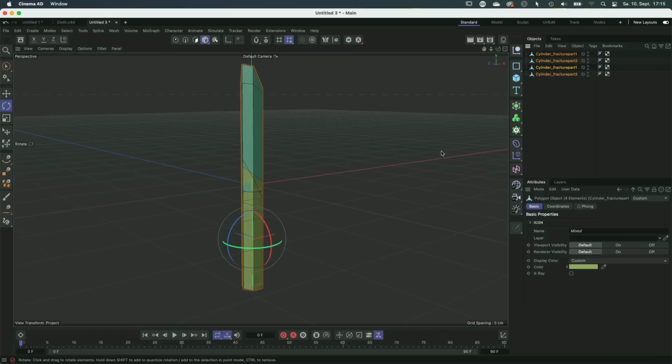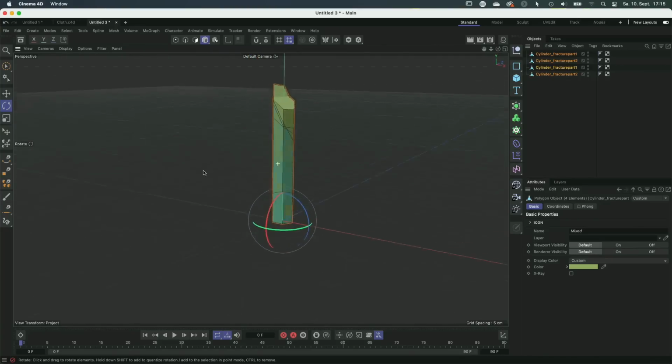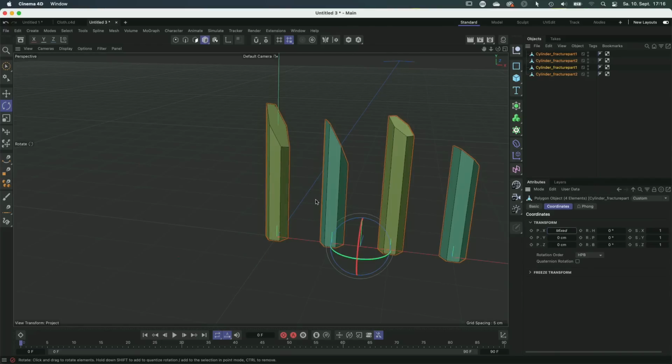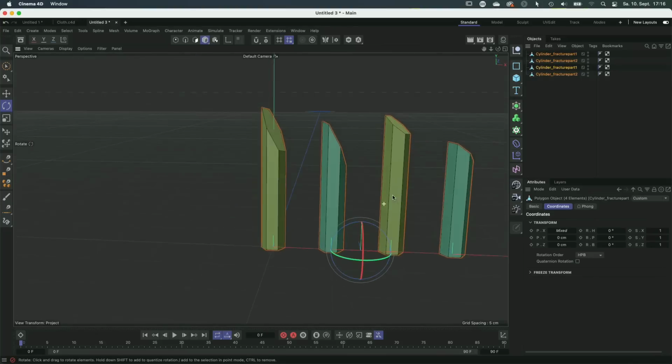Now I can reset the transform here by using the shortcut Alt-0. And you can see that we now have our crystals. So let me place them next to each other so you can see that. I'm going to do that by hitting a Num. Num is going to use the index of the selection, and then I can just multiply that by 5 or something, and I will have them next to each other. And yeah, you can see that's looking quite cool.